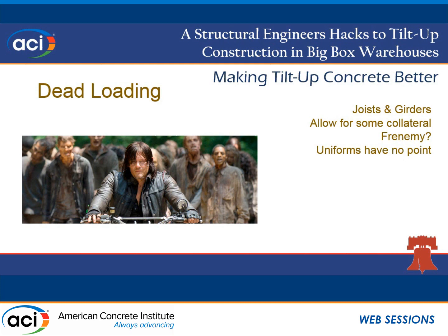You can also do the same thing in seismic. I usually don't in my initial design. But again, if you're carrying 5 PSF for collateral for fire protection, which all the wet pipes in the building added up was 1.5 pounds, you could reduce your base shear. But I usually save that one for later on, and if I have trouble making something work. So seismic, again, when you're dealing with dead loads, you want to account for it conservatively, but it's going to be sometimes working against you.